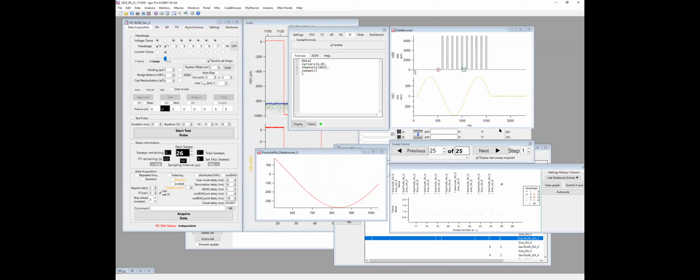And then you can just extract that part. And you can also say, well, I want to do things like, okay, I'll take the minimum from that. And this is this value. Or you can say, well, I want to have the minimum and plot that versus the mean value of something different. And we use the cursor range again, but now from the AD0 channel. And if you do that, of course, the Y value didn't change, but the X value changed.